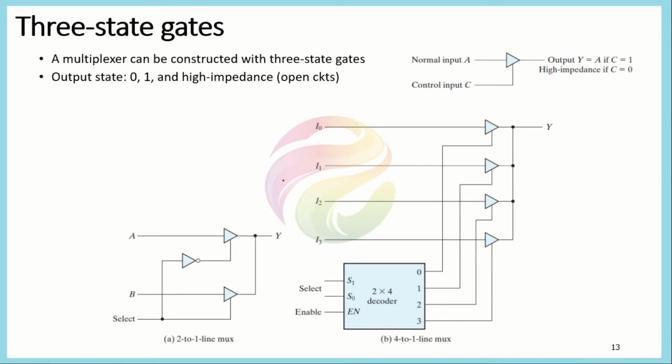Generally, this is not the case in most circuits, as sometimes we also have another state, which you can call an open circuit. In an open circuit, our signal is neither connected to the ground nor to the VCC, and it behaves very differently. The behavior of an open circuit, or the level at that open circuit, is generally known as high impedance. We also represent it as Z.